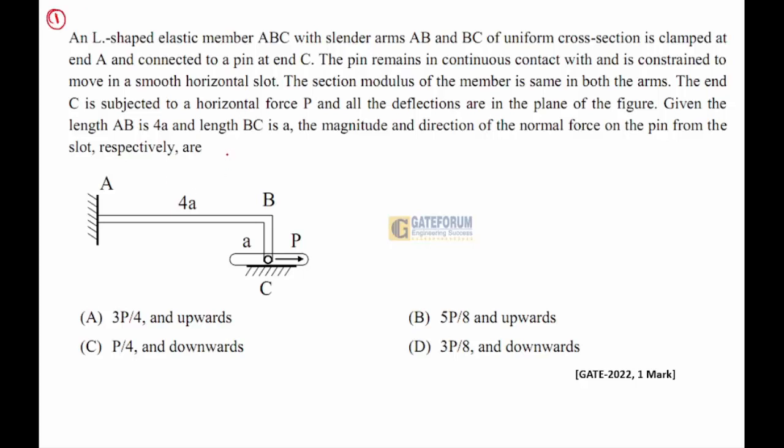An L-shaped elastic member ABC with slender arms AB and BC of uniform cross section is clamped at end A, that is at this point, and connected to a pin at end C. The pin remains in continuous contact with and is constrained to move in a smooth horizontal slot. The section modulus of the member is the same for both the arms. The end C is subjected to horizontal force P and all deflections are in the plane of the figure.